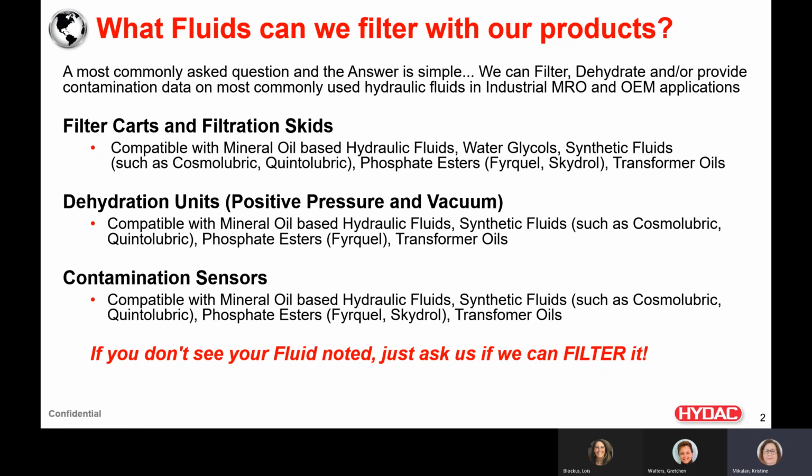We can filter water glycols, synthetic fluids such as your Cosmolubric or your Quintalubric, phosphate esters, commonly used Fyrquel and Skydrol, as well as transformer oils. For dehydration units, both our positive pressure and vacuum type style, these are going to be compatible with any of your mineral oil-based hydraulic fluids, your synthetic fluids, phosphate esters, particularly just Fyrquel, and transformer oils. Note we've removed water glycols from dehydration units because you do need water in the water glycol fluid so it will function correctly.